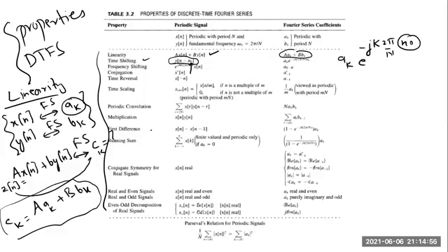The one difference that I will emphasize here is that in the case of discrete time, we don't have a derivative, we have a difference. In place of the first derivative, we have the first difference. First difference means x of n minus x of n minus 1. What are the Fourier coefficients for this signal? The coefficients of x of n are a_k, minus the coefficients of x of n minus 1.